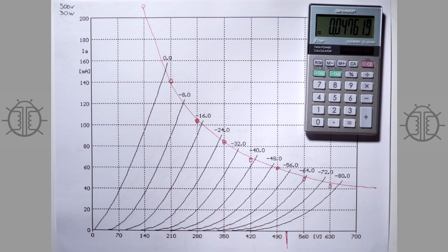So here's the difference between the resistive loaded and the inductively loaded stages. In an inductively loaded stage, your supply voltage is your operating point, and because an inductor will apply voltage to try and resist the change in current, the voltage will swing above the supply voltage. That's a pretty neat trick, and is why tube amplifiers are a great match with output transformers: you don't have to have a supply voltage of 800 or 900 volts, because your DC operating point can be fairly low.